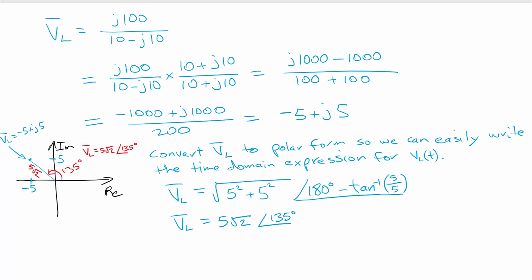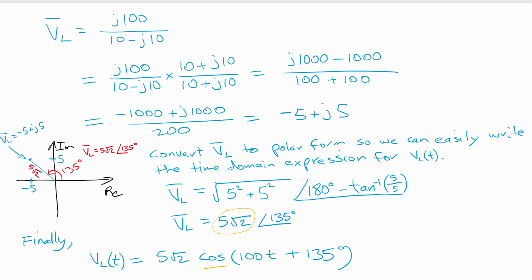So in red I've written the polar form on the phasor diagram. So we have both the rectangular form and the polar form here. Okay. So now the trick is to interpret this result back into the time domain. So this part is actually very easy, and what we're doing is we write cosine, and then from the polar form of the phasor voltage, we're dropping that down. So that's basically the scaling factor for the cosine wave. Okay, and then we drop the phase angle, we add it to the argument for cosine,